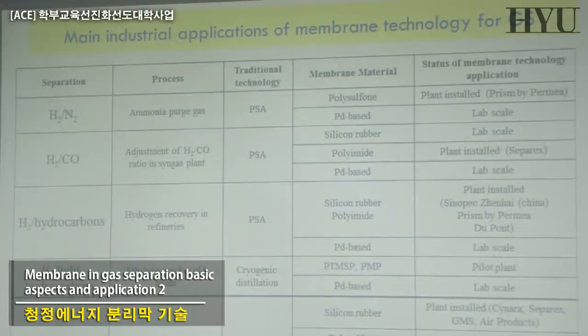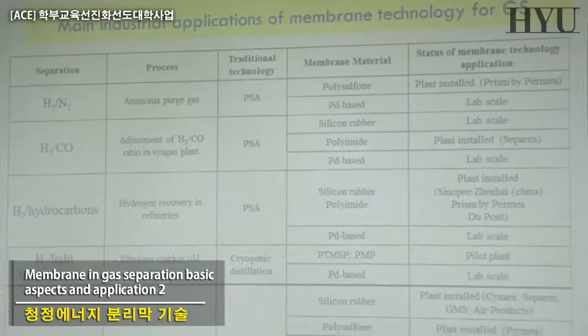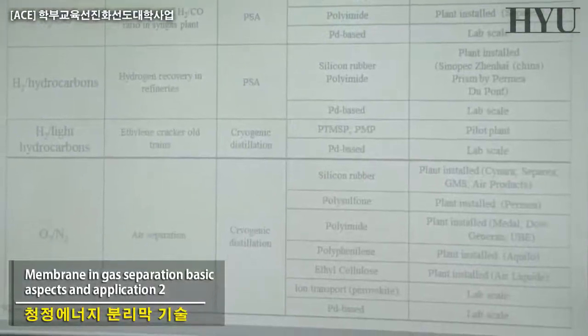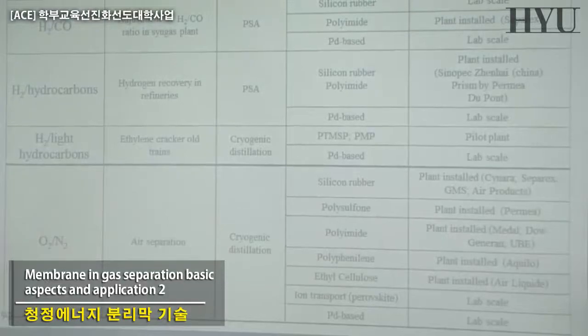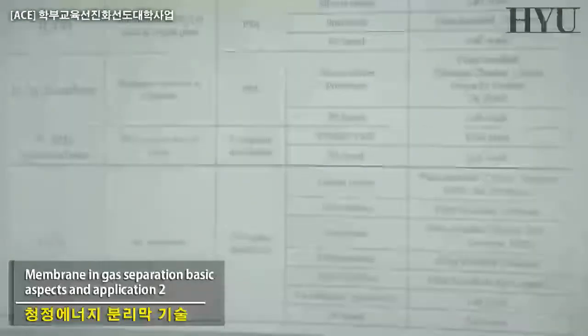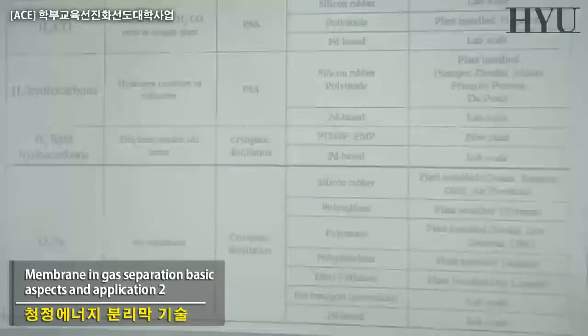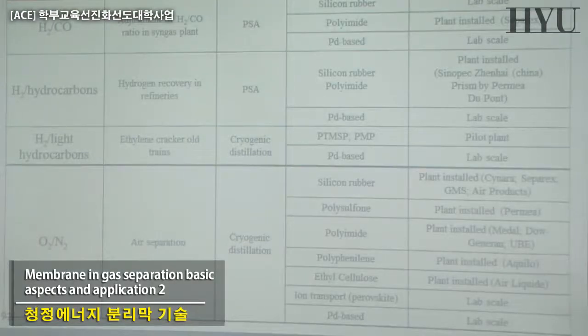The refinery was already existing. They were adding the purification at the end of the hydrogen. And they forgot that in the streams there were some ppm of some of the components that were used to clean the streams, that were 100% rejected by the membranes, accumulating on the membranes, and with time destroying the membranes.